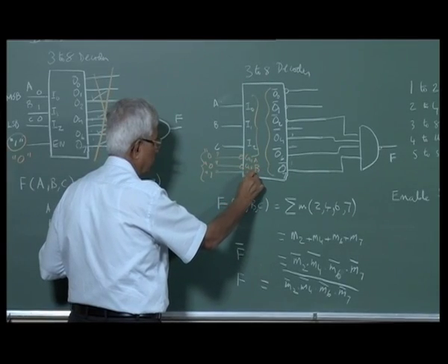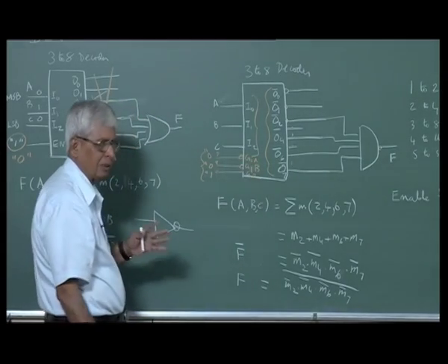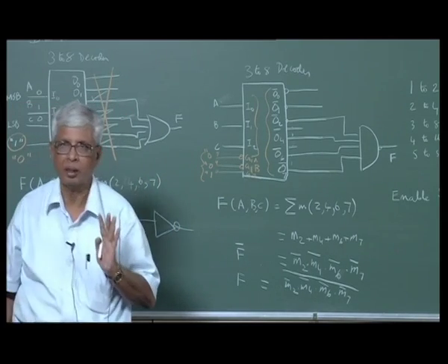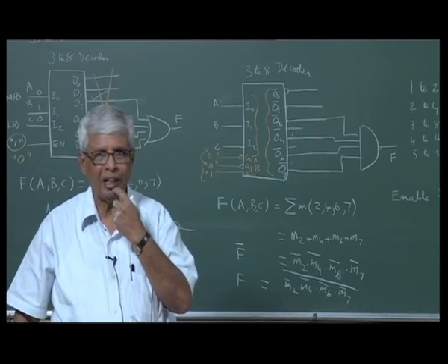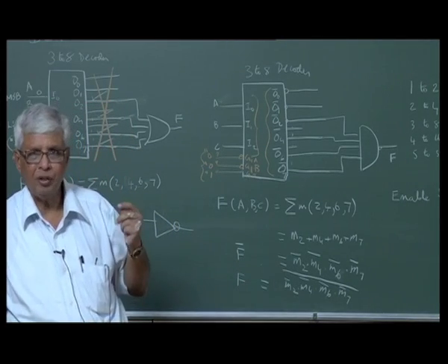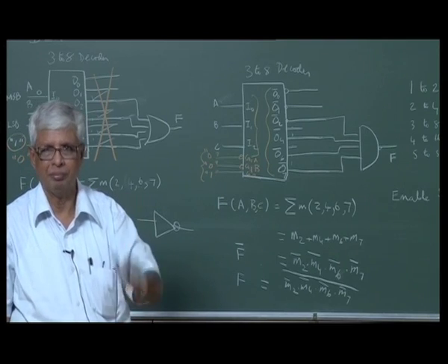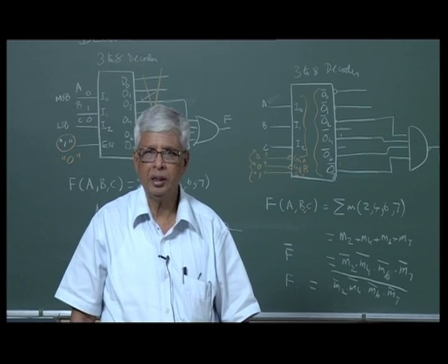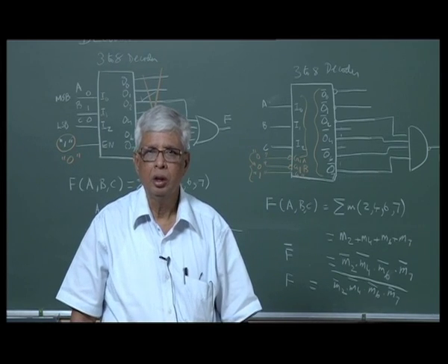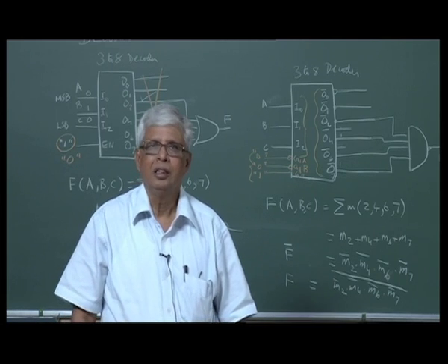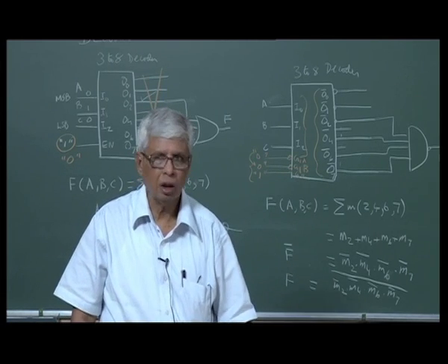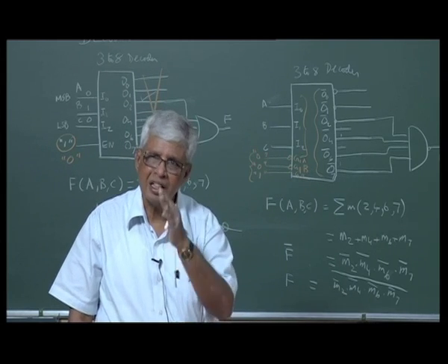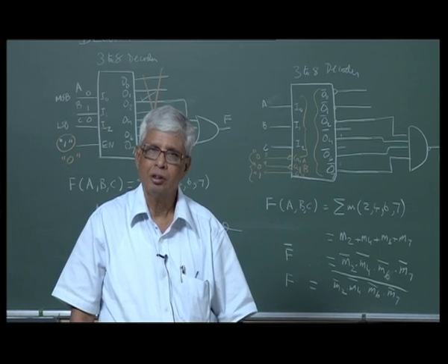and G2. As I said, this is only one particular IC I have in mind, it is called 74138. One advantage of this IC is that different manufacturers have standardized on the number. The 74138 is the 3 to 8 decoder with active low outputs. Whether Texas Instruments makes it, National Semiconductor makes it, Motorola makes it, or any other manufacturer makes it, they will generally use that number. It is not a rule again. You cannot go to court on this.